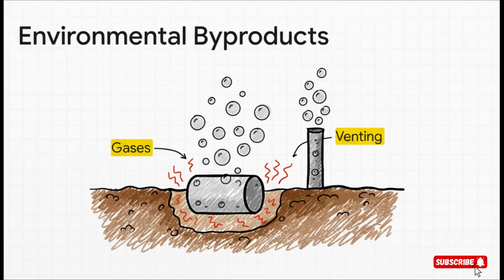So this chemistry isn't just a textbook exercise. It creates real-world byproducts that we have to manage. For instance, if you're in salt water, which has chloride in it, that reaction can produce hazardous chlorine gas. If you're using a carbon backfill, it can be consumed and produce carbon dioxide. These gases have to go somewhere, which is why deep anode ground beds are always built with a vent pipe to let them escape safely. And that acid buildup we just talked about, it can eat away at anode cables and really mess with the system's performance if it's not designed correctly.